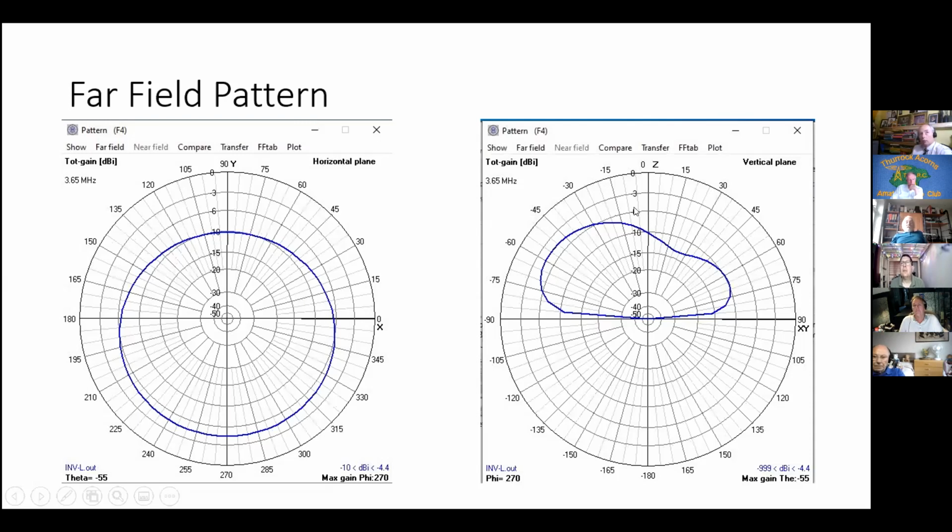It is pretty hopeless for NVIS because there is very little goes straight up. Even though the dipole has more gain, most of it is going to heat the ionosphere is the conclusion. Unless you can get the dipole well clear of the ground.